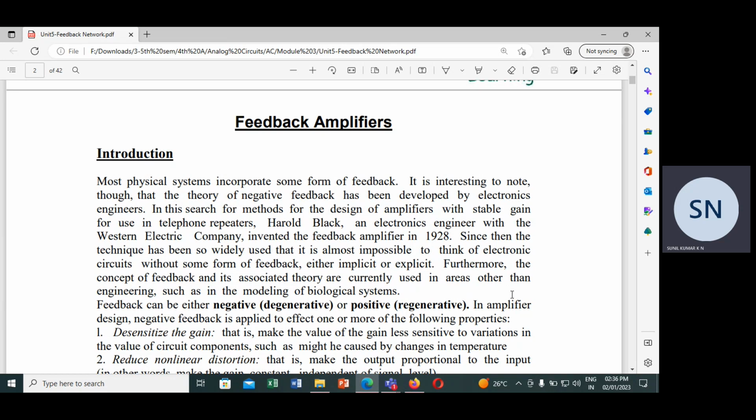Because by introducing the RS in the source terminal, the current flowing will be insensitive to variations in the external temperature or beta variation. So that is negative feedback by default, and those are the advantages we can get.